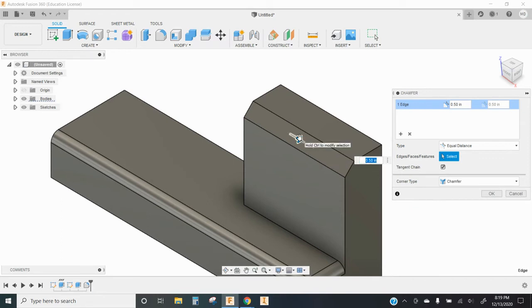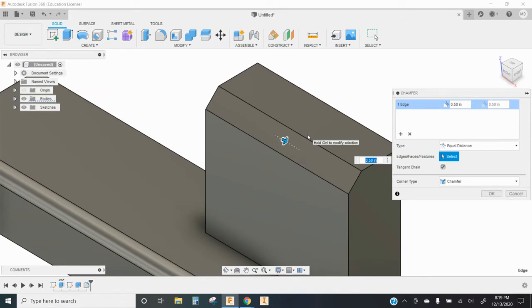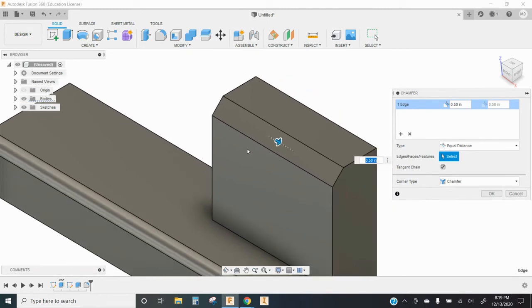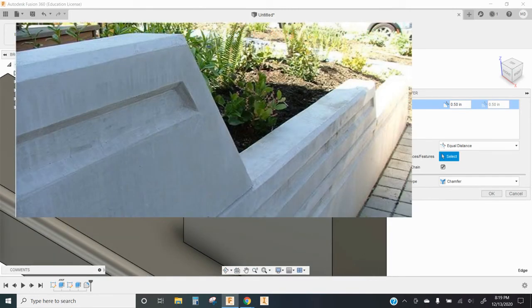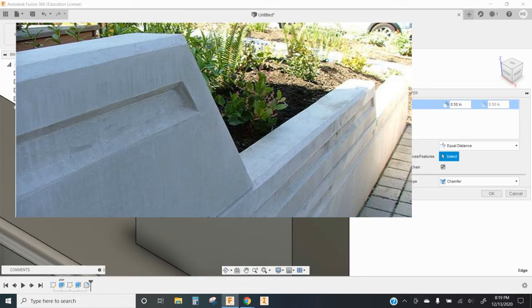And we see this in lots of designs. Sometimes it's just meant as a way to sort of reduce weight, or as a way to take the 90-degree corner off of something that could be brittle. We see this a lot in concrete. If you've ever seen an outdoor ramp or planter or staircase, very often the corners of the concrete will have a chamfer on them so that they're not going to be as likely to crumble off and get brittle when things run into them.